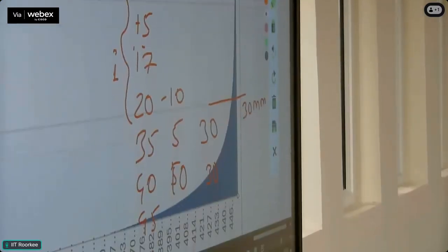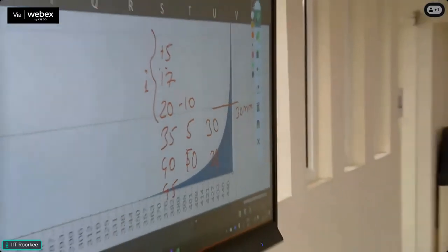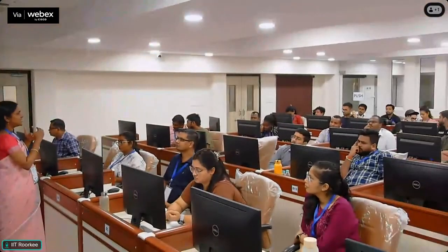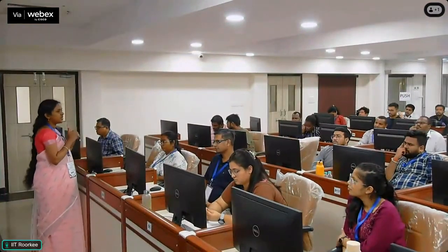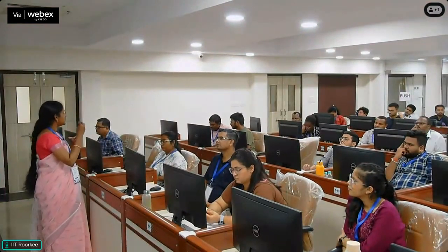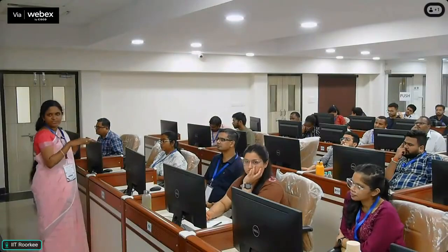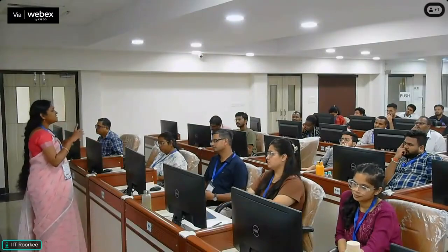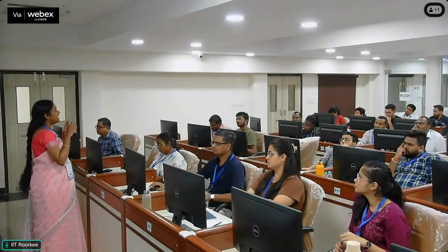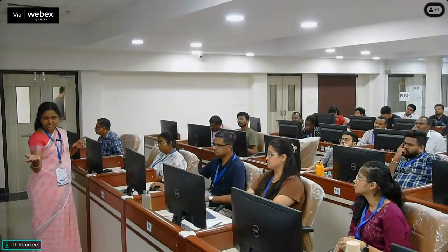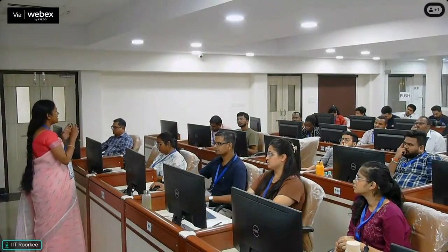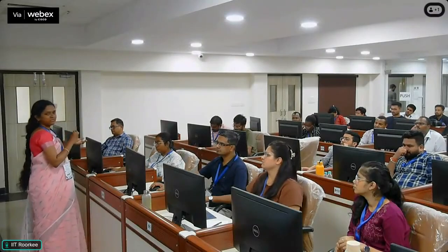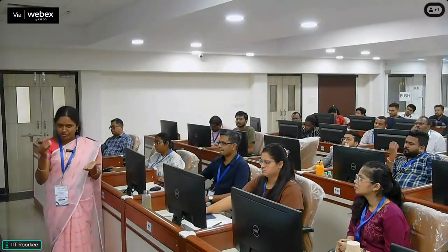I did it by hit and trial, but you can do it. We just want to make sure that at least, since we are putting some effort to design these LIDs, it should accommodate 80 percent of the rainfall. It is not about the runoff, it is mainly for estimating the pollutants. So at least 30 to 35 mm is needed. I think that is the amount which carries the pollutants, right?